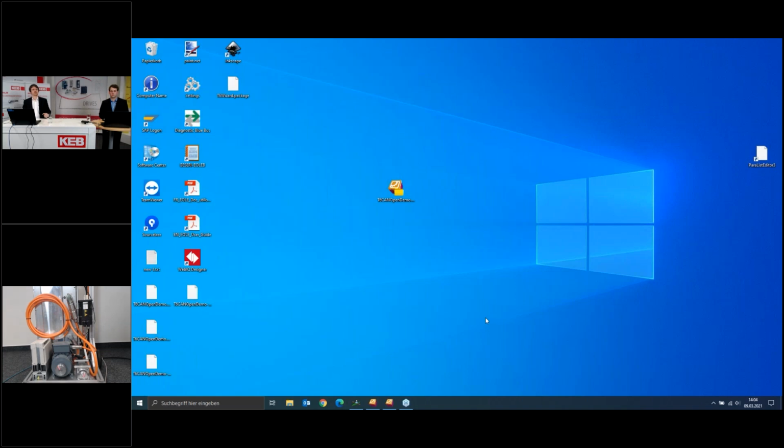For this purpose, I chose two apps, mostly because they are very different. The torque speed control app is a very basic app that is based on J1939 communication and just on torque and speed control of the inverter. The CAN open app is a totally different protocol. It's more common in the industrial area, but we saw that some of our customers also wanted to use the T6 via CAN open, so we implemented an app that could resolve this demand. With the app utility, you can basically choose which app is active on which node. And this is what I wanted to present today.